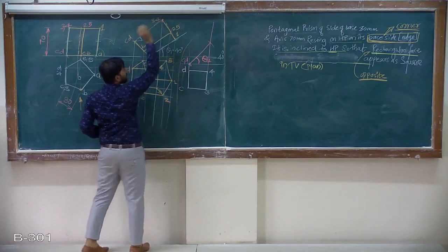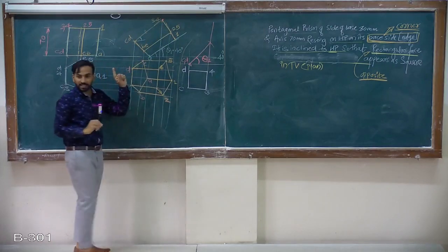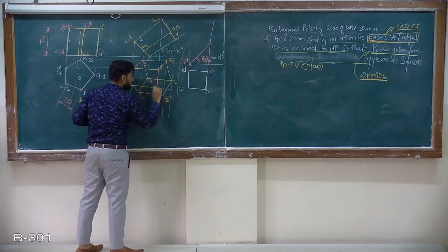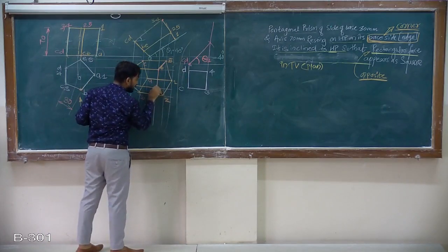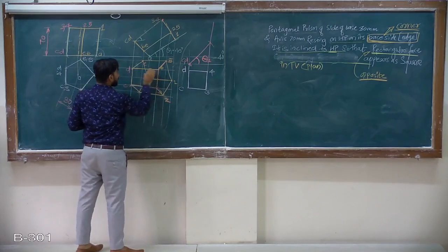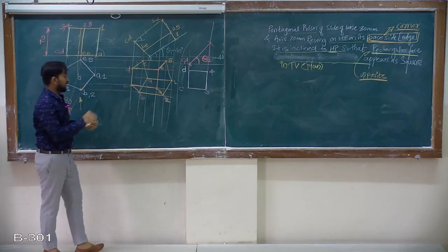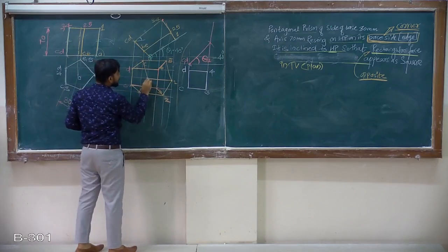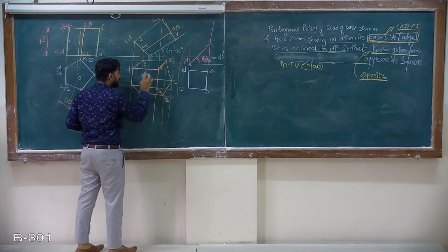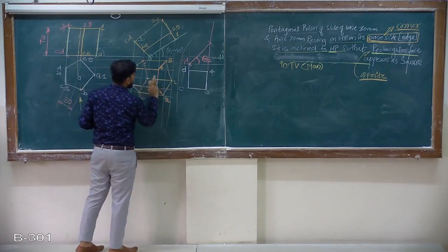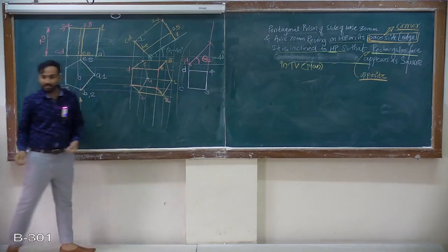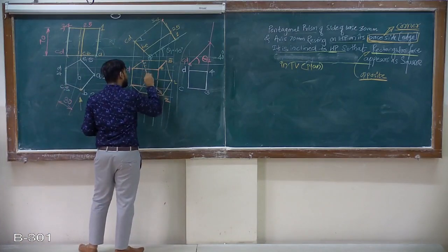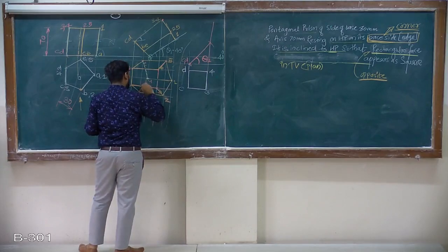Okay, so now I join everything as a visible line. Now observe here, 3, 4. So the line passing through 3 and 4 will be a continuous visible line. So 3, 4, all these lines are thick, whereas the line passing through the farthest point is A. So the lines passing through A, which are AE, AB, A1, will be hidden lines. That's it. So I'll just complete this.